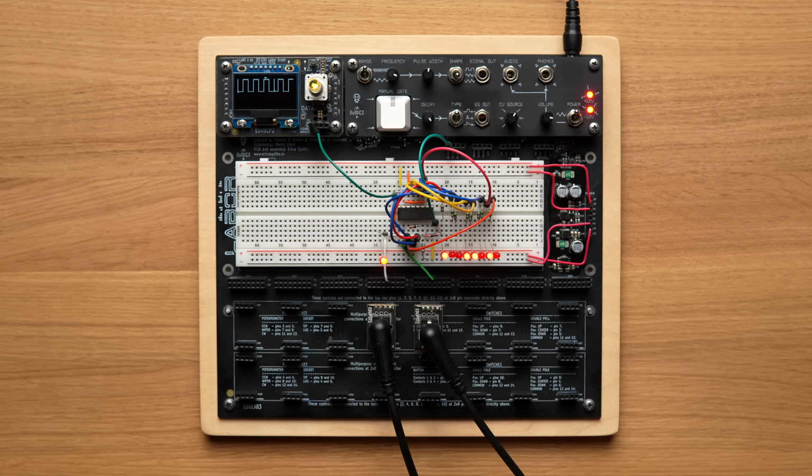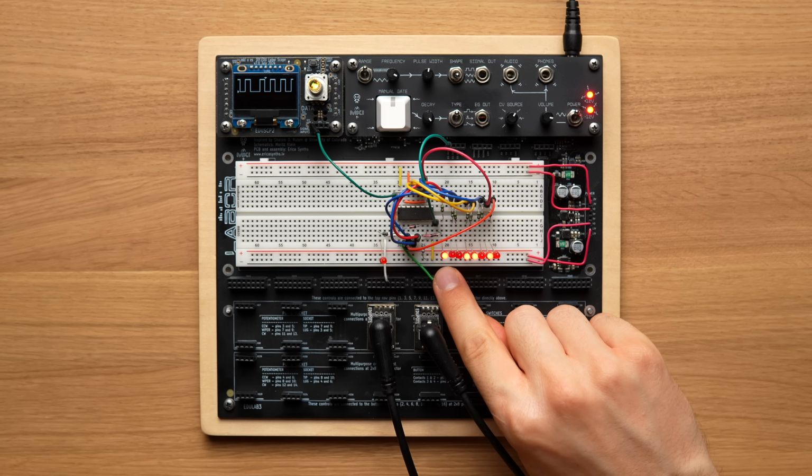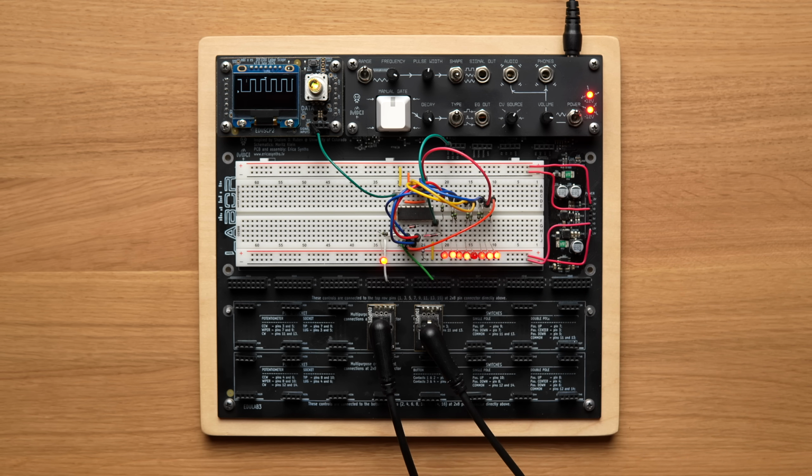What's up with that? Well, the issue is that our drum module gets triggered when its input voltage goes from low to high. We call this a rising edge. Take a look at our first output LED. Every time it switches from off to on, we hear a drum sound. But if 2 high bits appear in a row, the LED never turns off in between, so there's no second rising edge. How do we fix this?